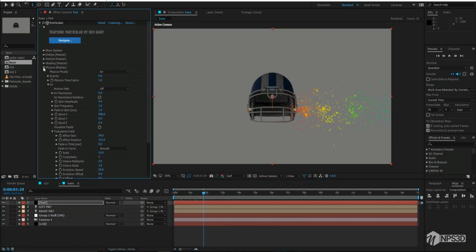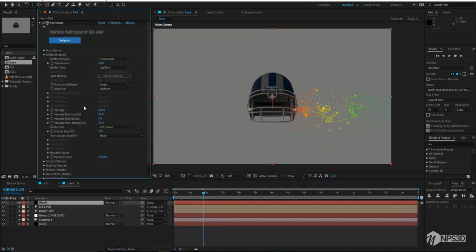And go to the emitter option, and here is the velocity, put down 0, velocity randomness put down to 0, and all 0, and here is the xy link, so choose xy individual and put 0, 0 and 0. So let me set it to 12, 12 and 12.